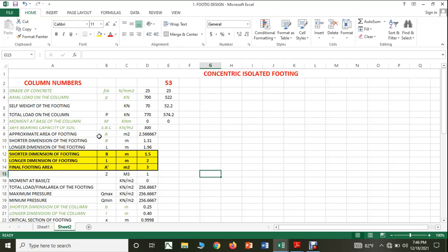So if you do the plate load test, you will know exactly the safe bearing capacity, and with confidence you can go to the designs. Therefore my sincere suggestion, students, is that as an engineer you should be in a position to convince the contractor or client to go for the plate load test. You should explain how much amount he is going to save if you do the plate load test, and what the advantages are. When we did this project, I made the contractor do the plate load test. A plate load test can be done even if you have a diploma college or ITI college in your area, right?